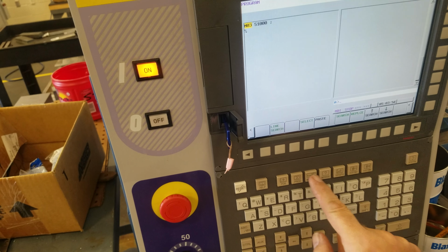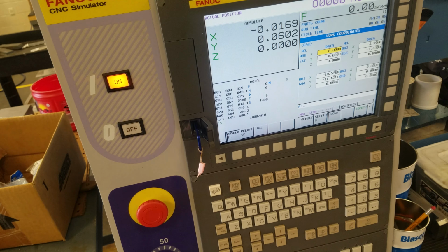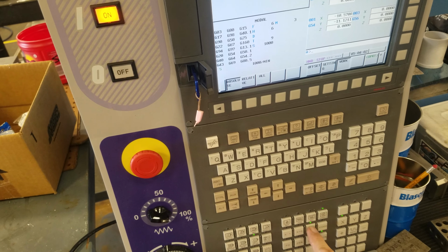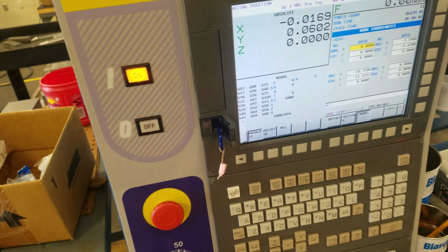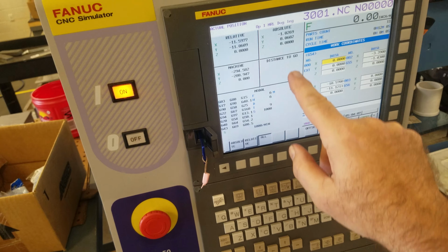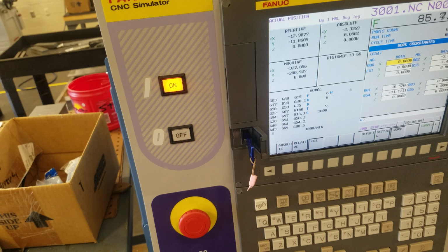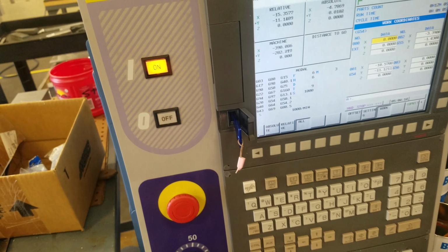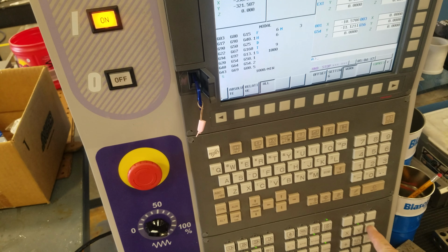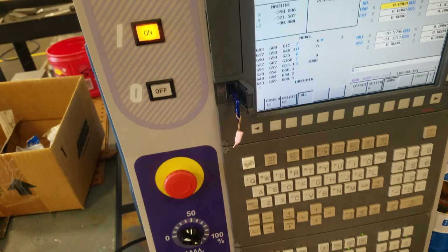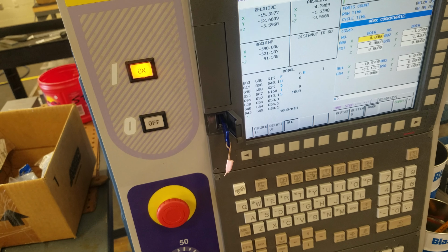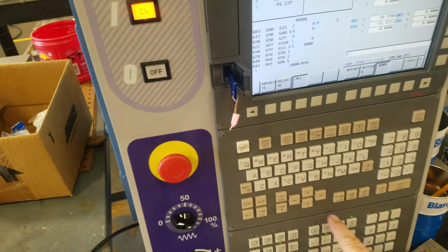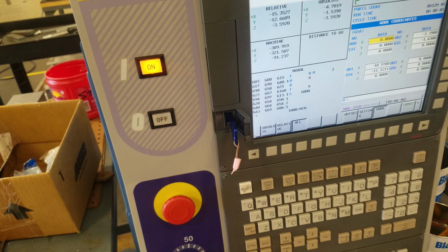So I would now switch to offset, work offset, handle jog, x-axis, make it the large button, and then start cranking. I'm going to switch this to the all screen, so I've got relative coordinates there. I move it over, get it close, bring down the z-axis, and I'll edge find. I'll put it in 1,000th increments and move it to the right a little bit. And if I'm happy with that one, I'm in the x-axis, moving it slowly.